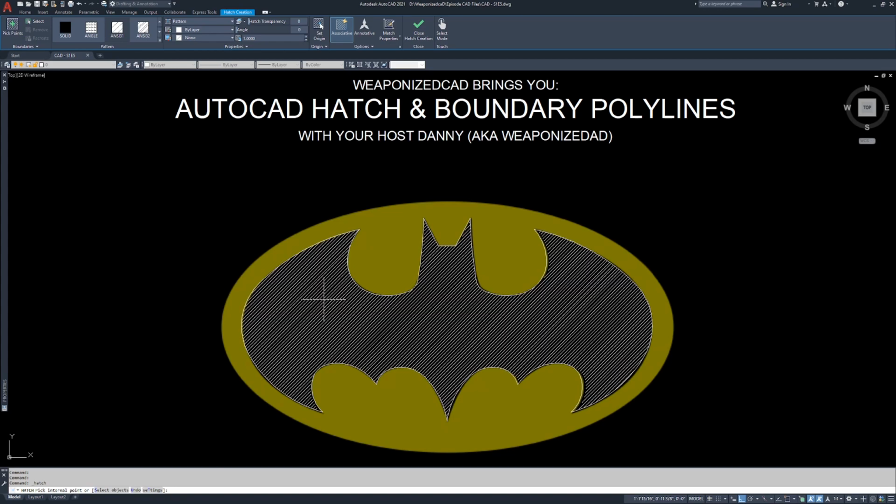Now, depending on what you're hatching, you're going to either pick that internal point, like you see my cursor is just hanging over our bat symbol here, and it's giving us a preview of what the hatch is going to look like. There are other times where you want to select objects. You might have things laying over top of each other. You might want to hatch something that's underneath, that's above, not the whole thing.